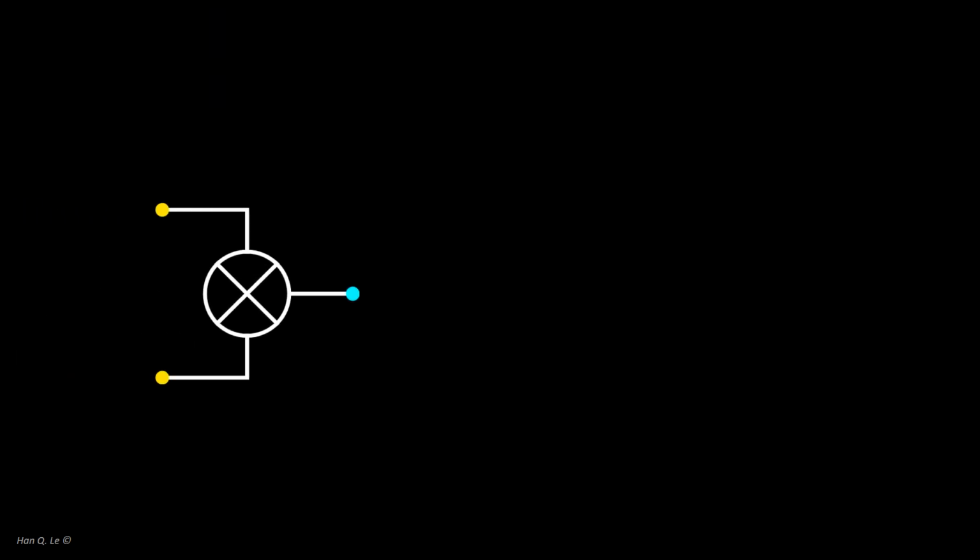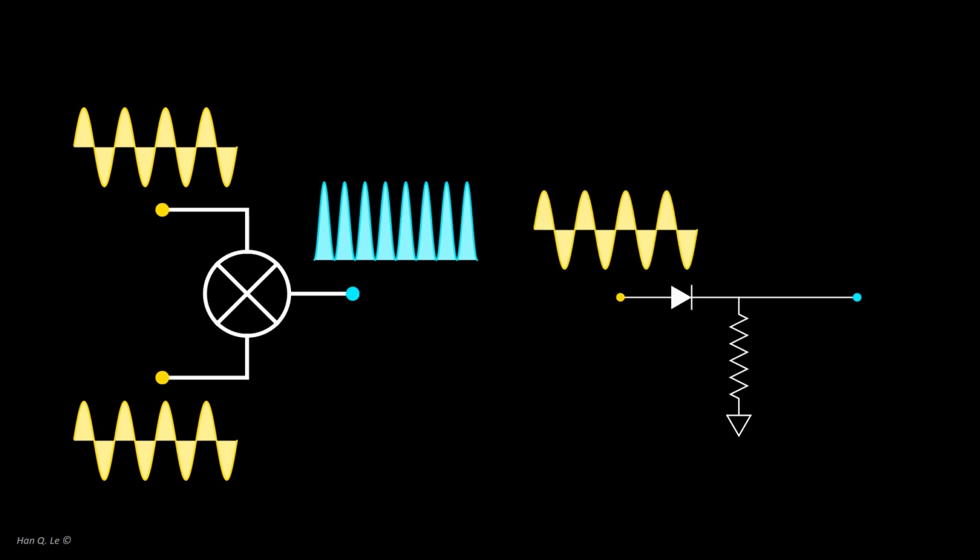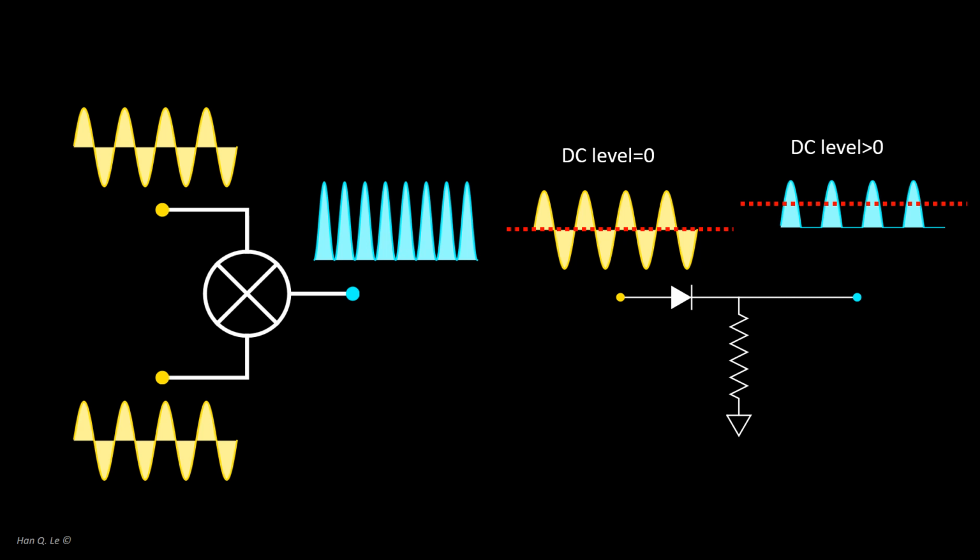In common practice, a signal AC power detector, such as a nonlinear mixer on the left, would be best to use to detect the bandpass filter output to demodulate the signal. However, such a device is not included in your electronic kit. Hence, one can use a simple diode as shown on the right, which simply rectifies the positive portion of the signal voltage, so that the signal has a DC level, which can be extracted with a baseband low-pass filter.